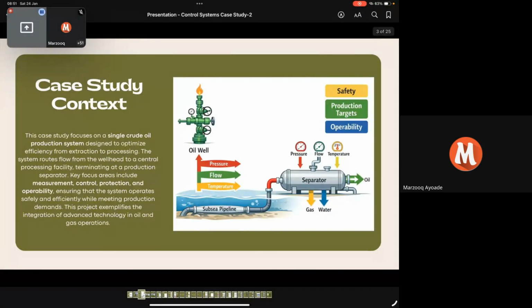For the second question, as-built. When you have done your design engineering and produced your P&ID and other documents, during installation and construction, we are not perfect, so we make some modifications here and there. Once we make that modification, we need to document it. After installation, we update the drawings we created during design engineering, and that becomes the as-built, so that people who want to maintain and troubleshoot down the line will have the correct information about the plant.